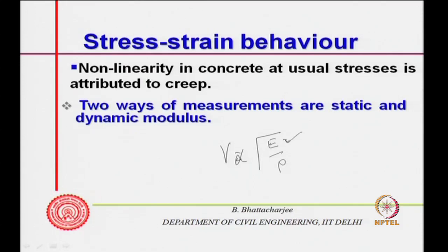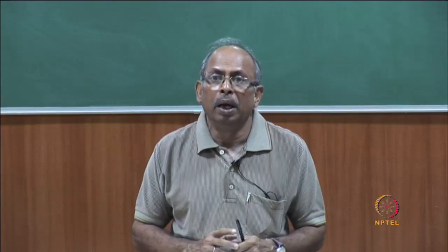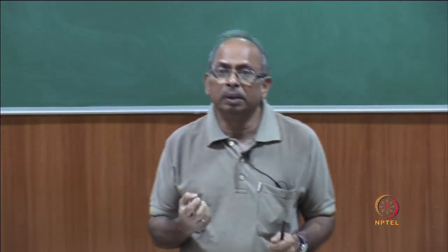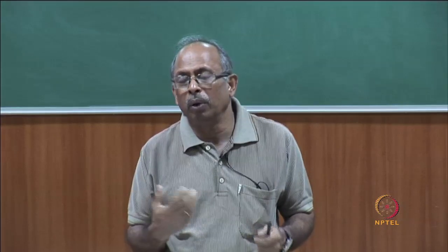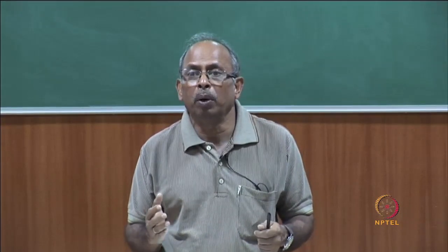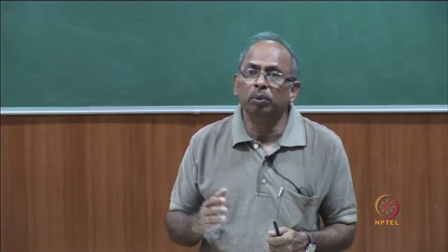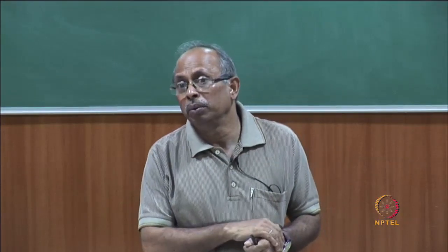So, therefore, modulus of elasticity has something to do with this velocity, the mechanical wave or sonic velocities, pulse velocities. When a wave is traveling through a solid, there is compression and rarefaction, a longitudinal wave traveling through it, or any wave traveling through it, there is deformation, and therefore the modulus of elasticity plays a role. But what kind of modulus of elasticity? That would be bulk modulus. So, you can relate this to velocity.